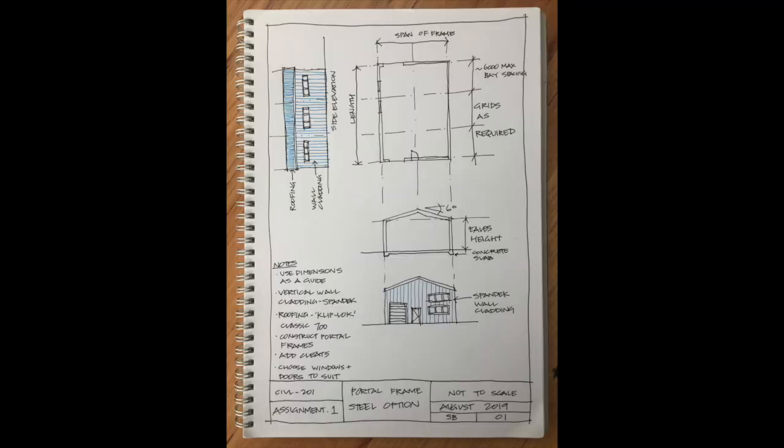The specifications of the design were to have a structural slab 400mm thick with at least 10 windows, 2 doors, and a mezzanine 4 metres off the ground, covering an area of at least 8 by 5 metres. The spacing between the portal frames must be between 4,500 and 6,000 millimetres.